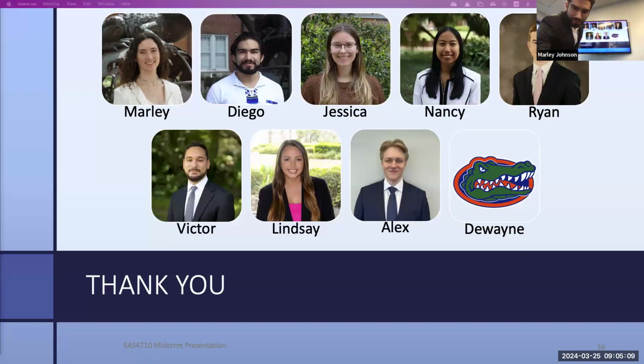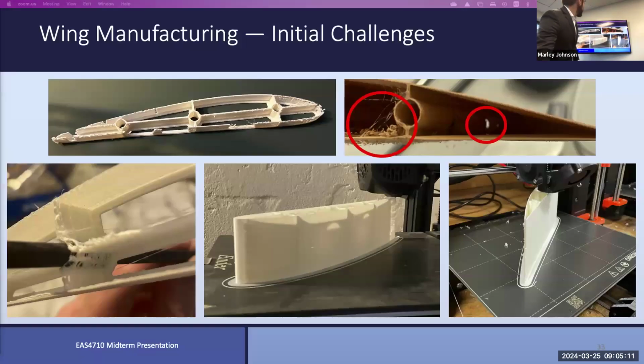And the other issue with the lightweight filler is that it's not too firm. So if you want to get increased rigidity, you'd have to make it thicker. And from what we've tested, applying the lightweight filler and then the carbon fiber is reasonably a small increase. It doubled the size of the lightweight filler, but still for our target rate, it is within the range of what we want.